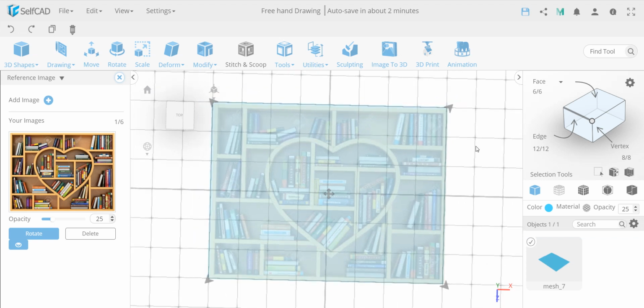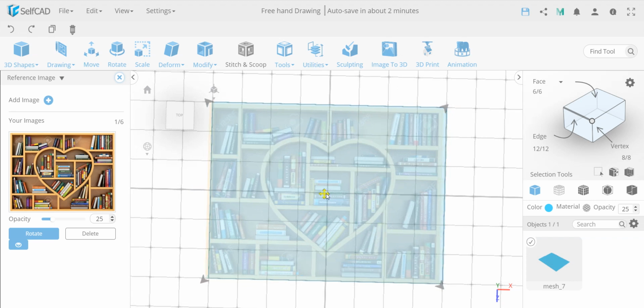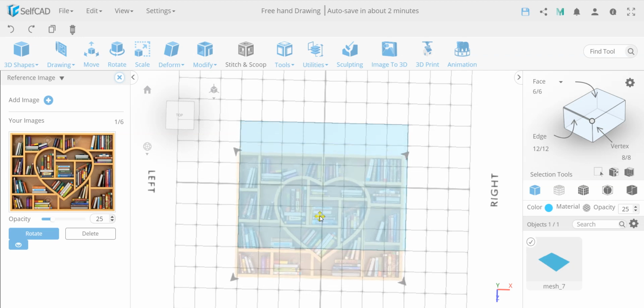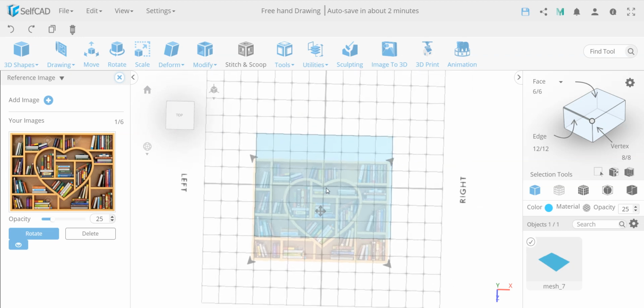So I'm going to misalign it from this cube, no longer need that reference obviously. But as you can see, I need to align this so I'm going to have symmetrical, and I'm aligning it this way. I only care about aligning it on this direction, the X direction. I can actually move it down a little bit, and that wouldn't make a difference because I'm going to be drawing symmetrically just on this direction. And in general, I don't like things to be close to this, because if you draw and it's close to this, your mouse will stop working because it will intersect these tools, and this kind of blocks the 3D movement. So I don't like to have things very close to that.